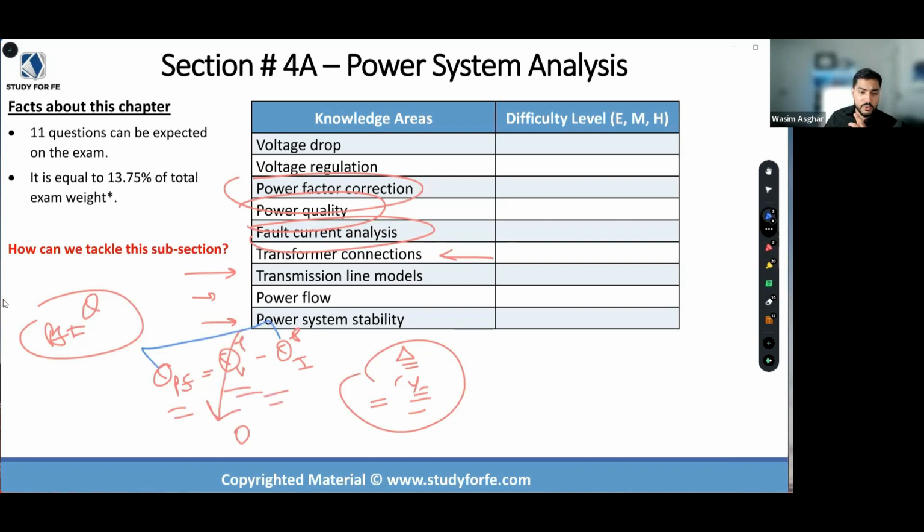Polarity flip. So students are looking at the current angle and they're saying, I thought that the angle is supposed to be positive when we have a lagging power factor. That's true, but you got to spell it out completely. Power factor angle has to be positive when we have a lagging power factor, not the current phase angle, right?